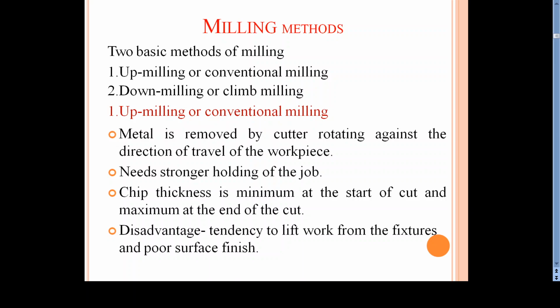It needs stronger holding of the job because there's a chance of lifting of the work or job because both are in the opposite direction. So we need to hold the workpiece very firm. And chip thickness is minimum at the starting of the cut and maximum at the end of the cut. Disadvantage is a tendency to lift the work from the fixture and the surface finish is also comparatively low.